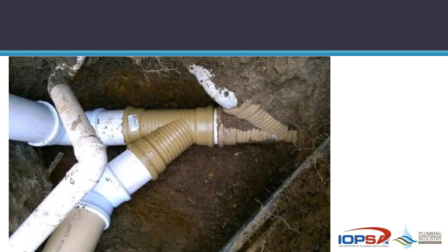So as far as access is concerned, guys, it's straightforward. Show the places where it's required. It always refers to full bore access. It refers to slow or long radius bends. If you stick to that, there's no way that you can go wrong. Sounds simple enough, but yet these things do get failed, and I don't know if it's a lack of supervision